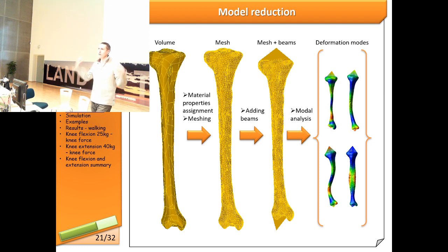So instead of solving the whole model, you use these modes, which are a simplified version. Of course, this causes some loss of accuracy, but once you get the model running with that and get all the final things, then, if you really want to get full accuracy, you can run the full model just once, solving it for good. But first you can experiment with the deformation modes and, in most cases, you will get good enough solutions even for stresses.